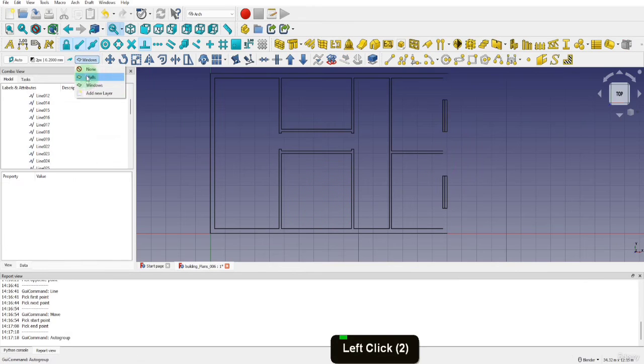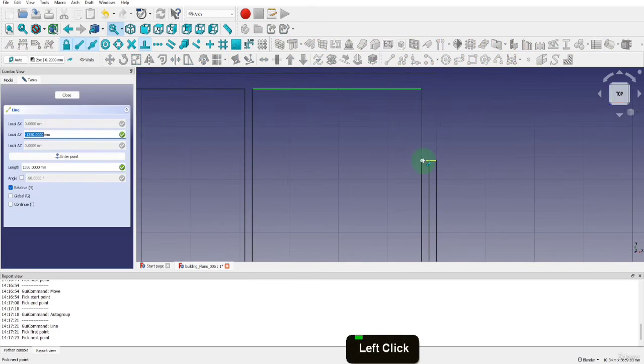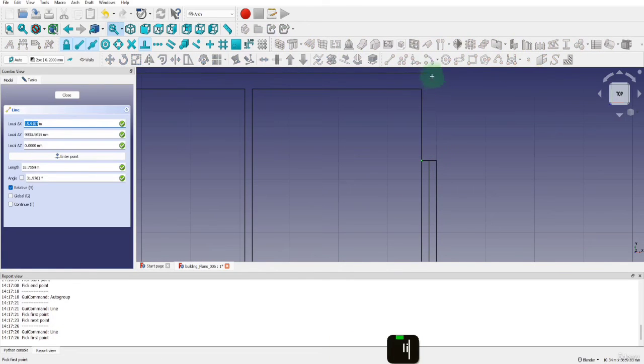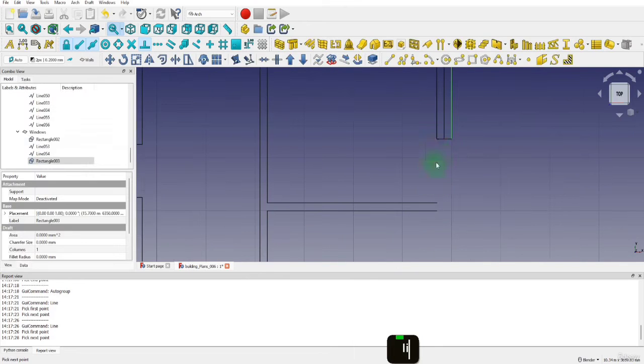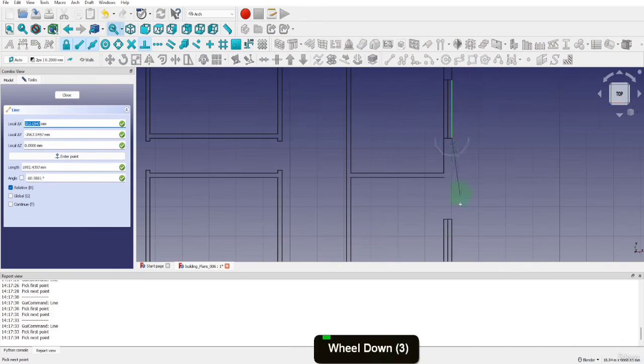We can draw in lines that only connect to the windows and don't overlap. Select the line tool and draw lines from endpoint to endpoint. This will make modeling in Blender easier. The shortcut LI works well here and saves time with back and forth to the toolbar.